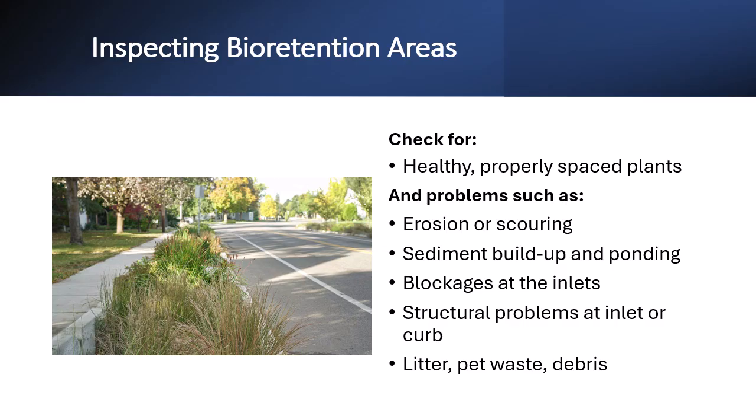And although bioretention areas help pond water for slow infiltration, there should be no standing water 72 hours after a storm. There should be no blockages at the inlet from sediment, litter, or debris. And check for structural problems at the inlet or curbs, including any damage, settling, or misalignment that could disrupt function.